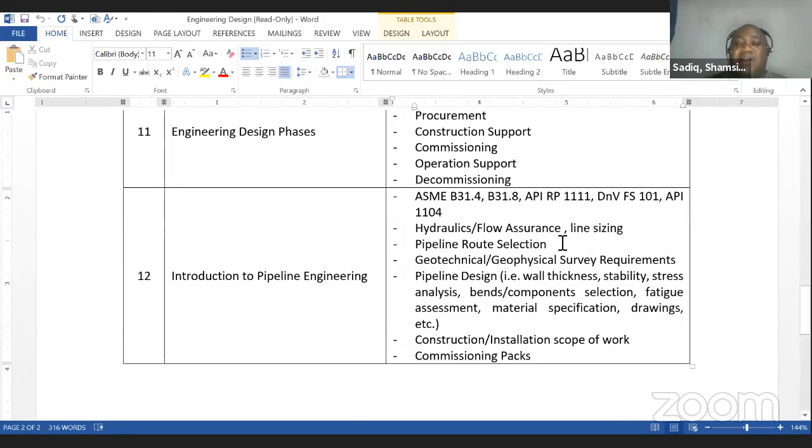With respect to salinity, yes, there's a standard coating that we apply, and that's another aspect of pipeline materials management. We have the coating expert that specifies that for these soil characteristics, this is the coating you apply. On top of that, we have the CP system, called the cathodic protection system, that is applied. All these are driven by the pipeline engineer managing its material resources person and the corrosion person. So all these are put in place.